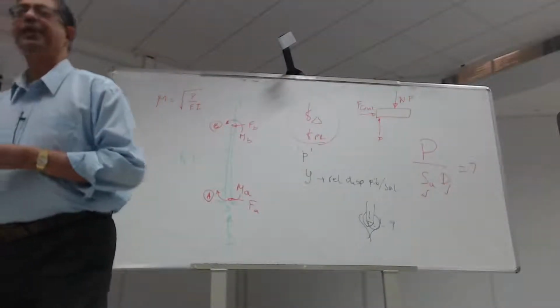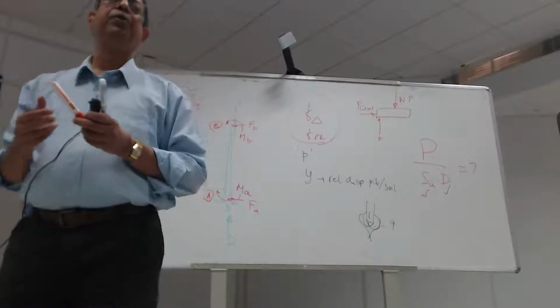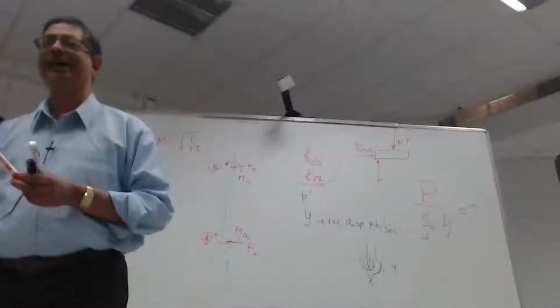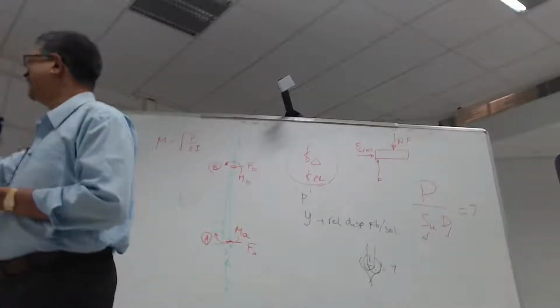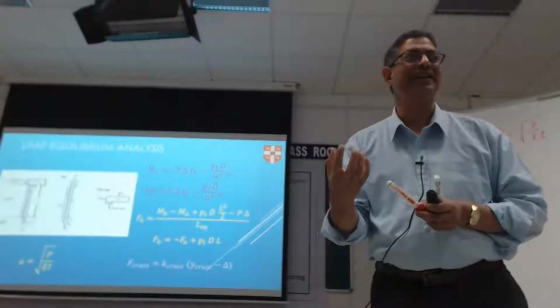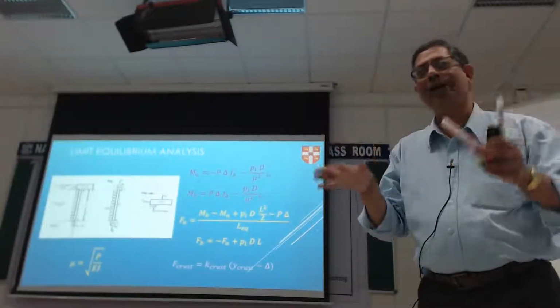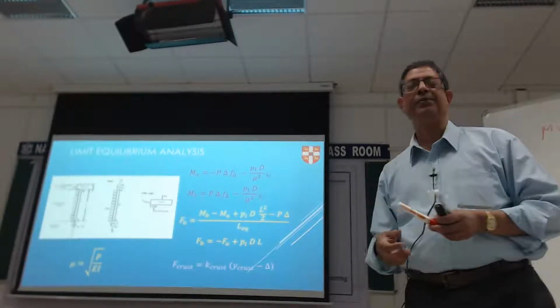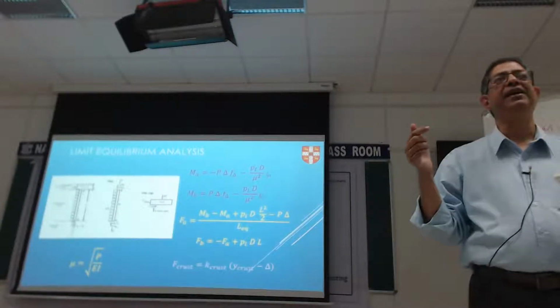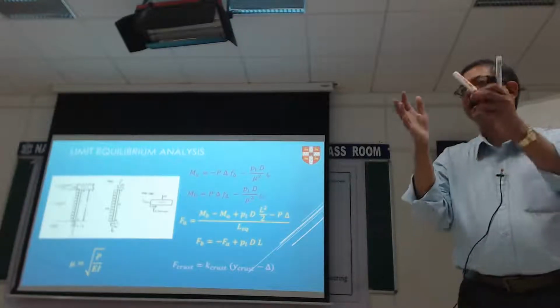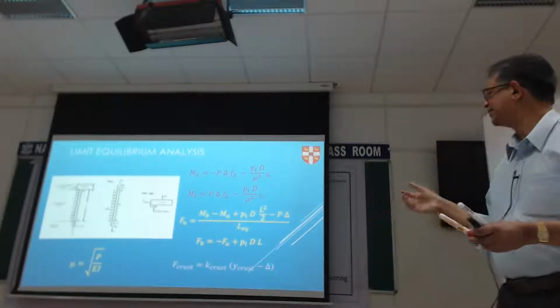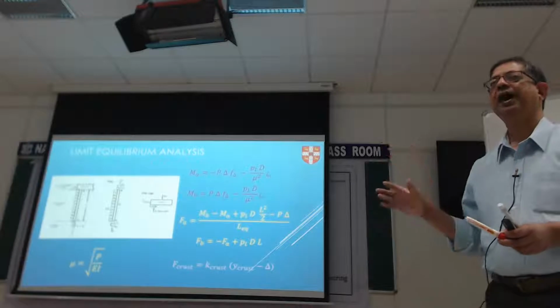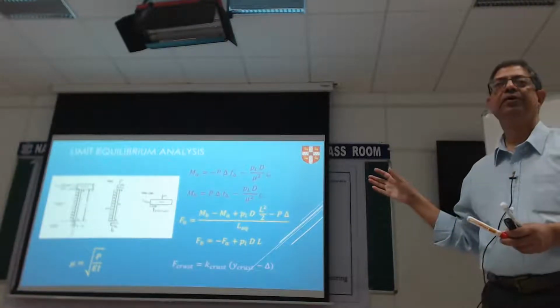So that you can estimate if you know the elastic modulus of soil. I hate this part. The K is like a spring constant for the non-liquefiable crust, and that times the relative displacement between the cap and the soil, which is how much the crust moves and how much the pile tip moves.